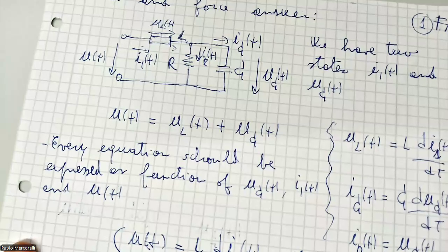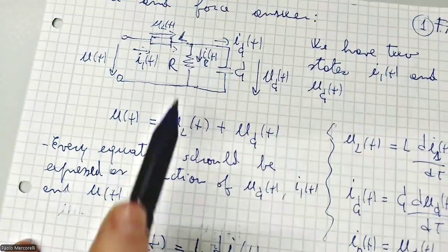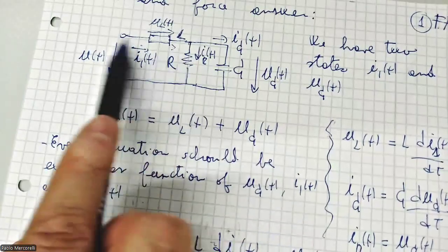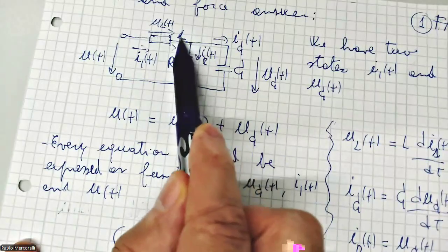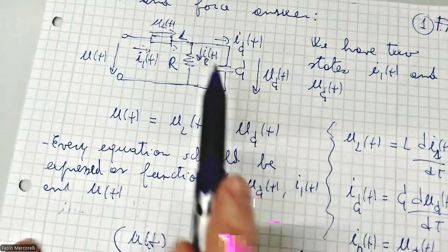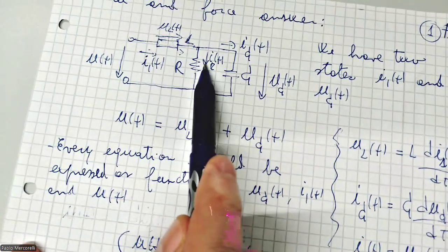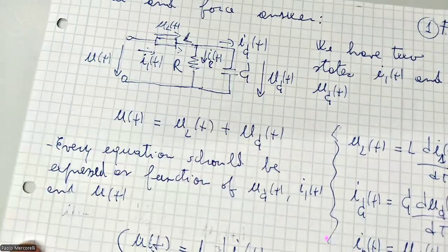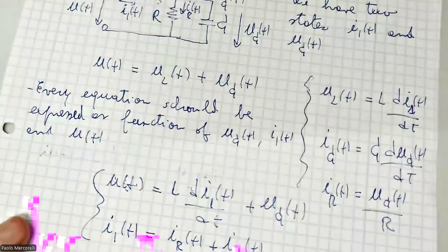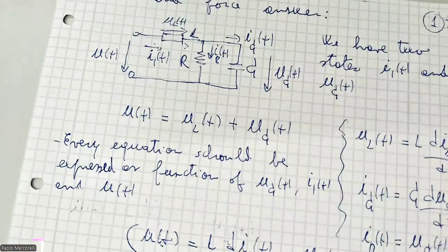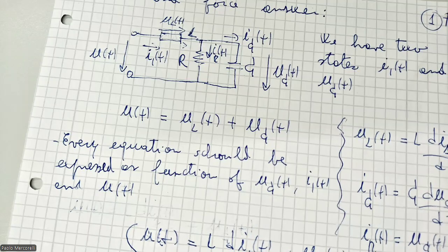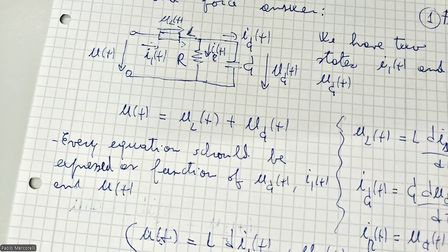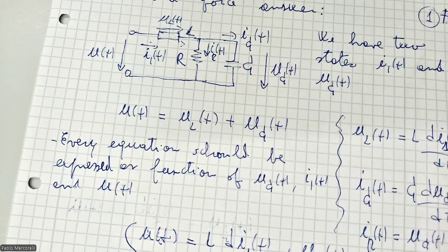The second equation which I am considering here is the node balance on this node here. Basically, here we say that the current which is going into this surface, so that, yeah, you can consider a closed surface node, equals the current which goes out. This means IR plus IC. Probably you know better than me. Now, as I told you, here I didn't indicate the second law of Kirchhoff, but anyway, this is the way to represent the circuit. Now, also here we have to consider states at input, if any.